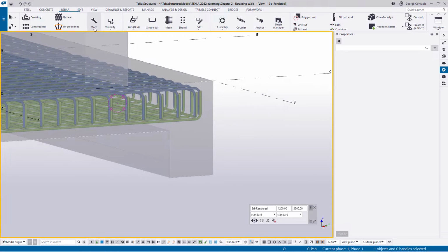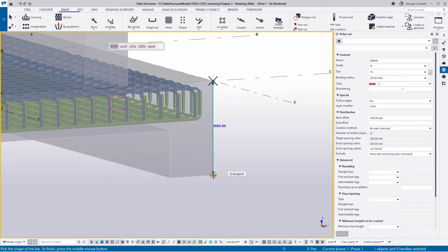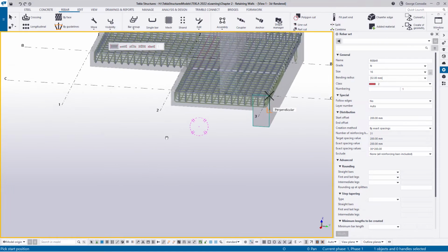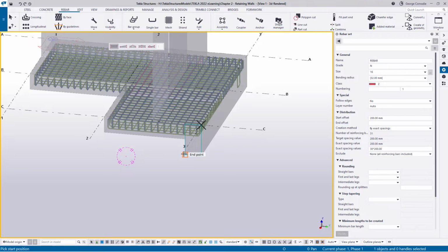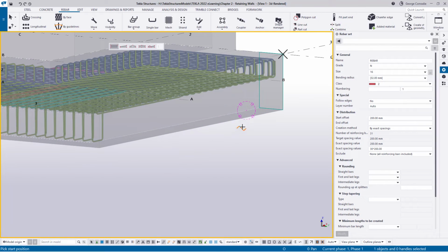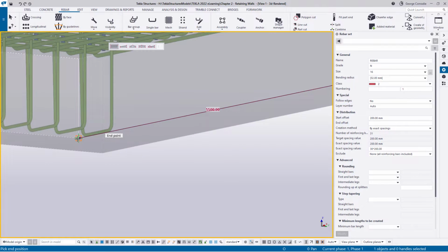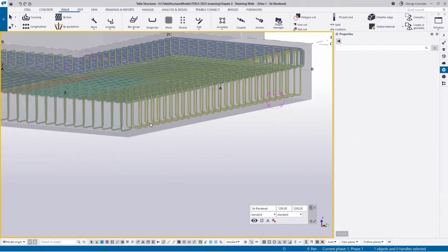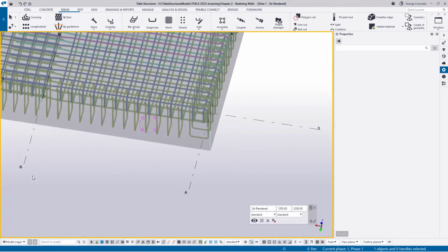So in here, we just repeat more point input. We start at the top, bottom, back, all the way up to the top and across. Accept that as the shape, and then for our guideline, our spacing line, we need to just have the internal bit. In other words, we go to the inside face and make sure that it doesn't overlap. So if we turn around, you can see these stop on this face and that stops short on the inside face.